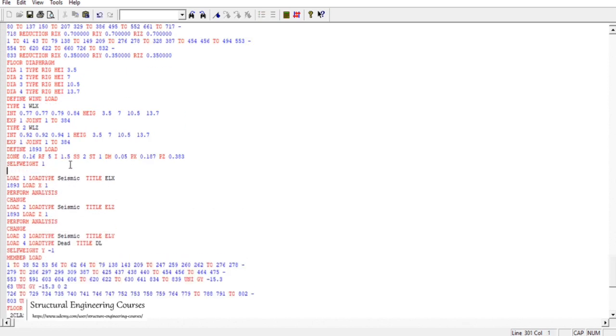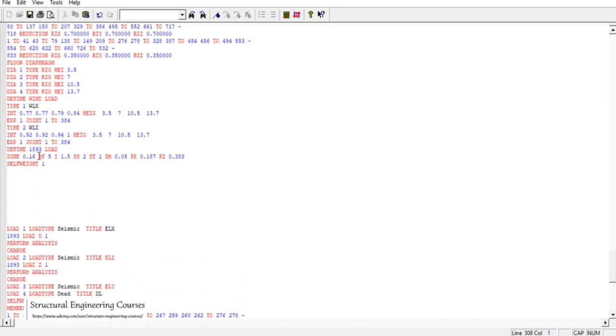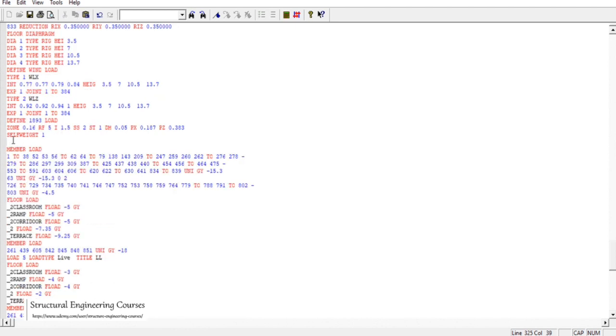So we go to the self weight 1 option here. This is the syntax in which the seismic definition is defined. Here we can just copy paste. As a token to remember, we can enter the stars here. We do need to change the load as weight, and after that we need to remove this minus sign and remove the GY here.